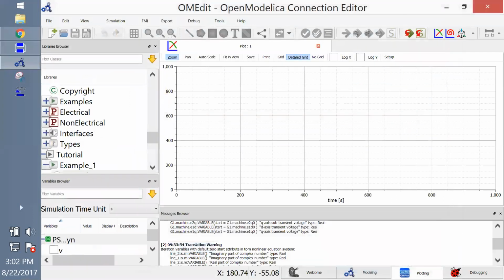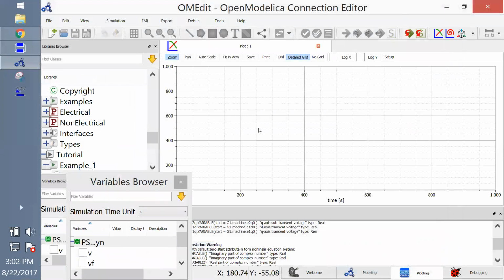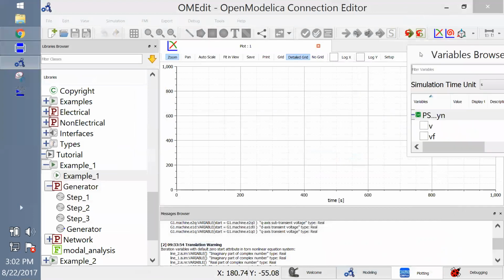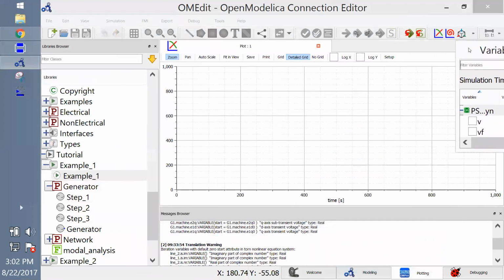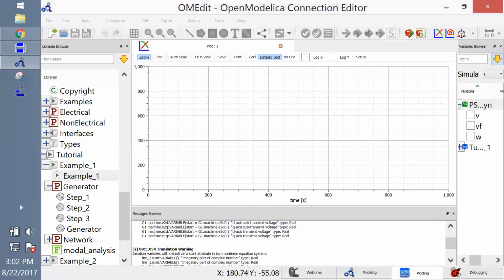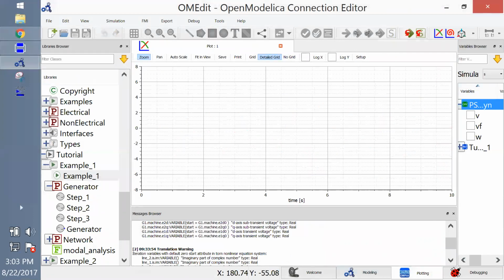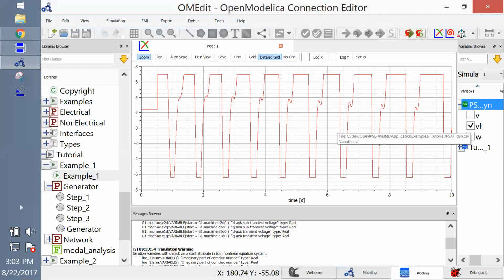And when you open this, you will have the simulation variables browser. I'm going to try to, there, almost. Come on, you can do it, there. So you just click and it will plot the, yeah. That's the field voltage, the speed, and some other stuff. What you can see here already is that the thing is getting saturated. So that's the point of doing this, just to load the variables so we can compare them afterwards.